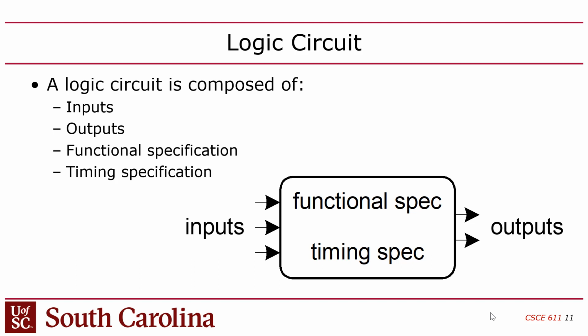In this class, we're using a very easy to achieve timing spec, which is 50 megahertz. So you're going to do some designs, and we're going to tell the tool, you got to place and route this in a way that you guarantee me that it'll work at 50 megahertz, regardless of what temperature the room is I'm running the FPGA in, because that affects the performance, the delay of the logic, and regardless of any manufacturing variations on the chips.